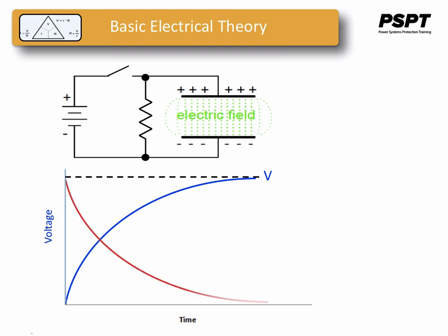Conversely, if a load resistance is connected to a charged capacitor, and the source of voltage is suddenly removed, the capacitor will supply current to that load until it has released all its stored energy and its voltage decays to zero. Once a capacitor voltage reaches this final discharge state, the current decays to zero. In their ability to be charged and discharged, capacitors can be thought of as acting somewhat like secondary cell batteries.